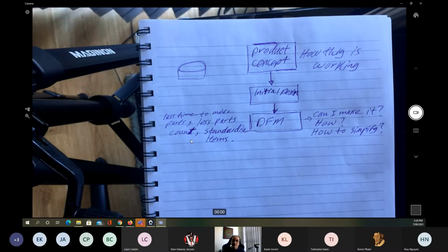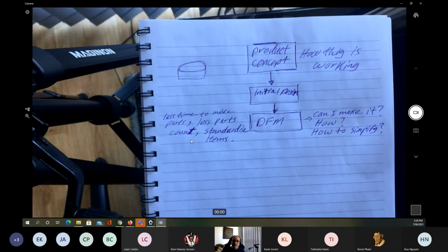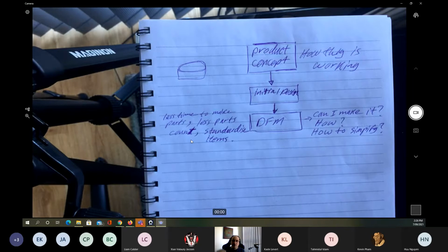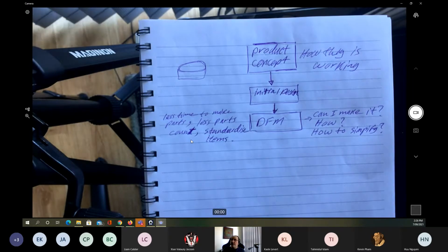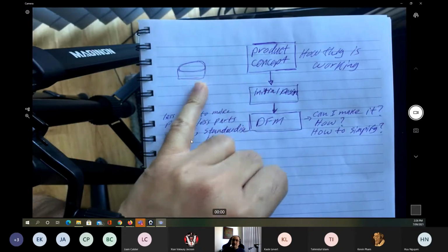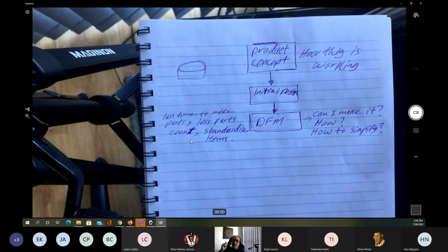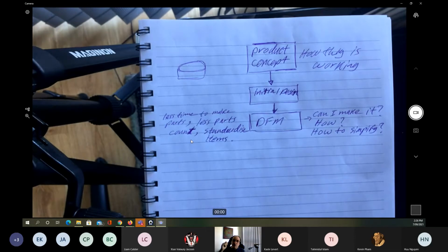We find that we have the 40 millimeter diameter, where 40 is the outside diameter. The inside is going to be 37 or 38. You can use the 60, you can use the 80, you can use 100. That's what's available in the market. So we standardize the item. I standardize the valve because I need to do that by casting. So I always have the mold, and I can use this mold to make multiple parts.